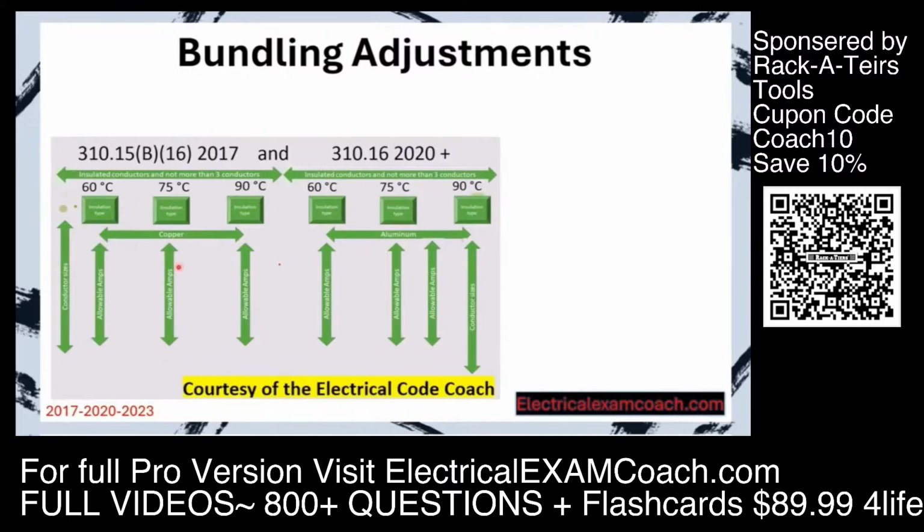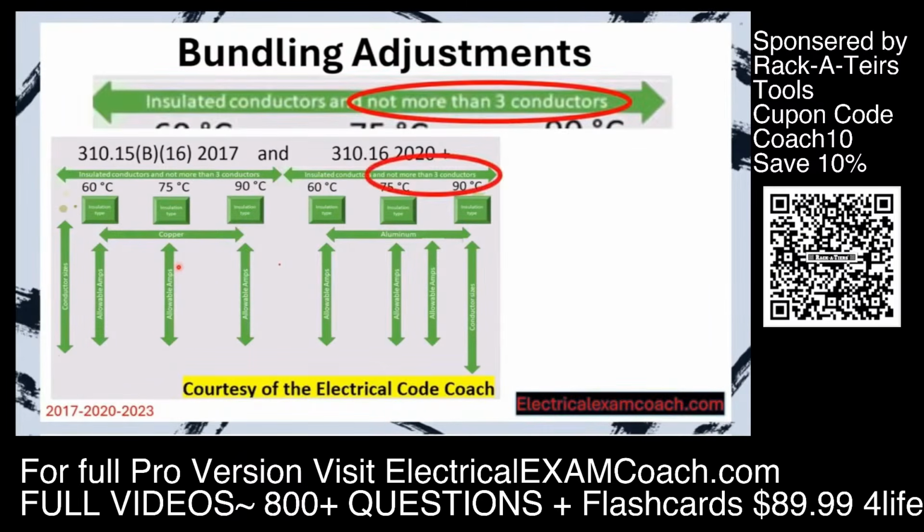If you look at the paragraph above the table, the one that I said we would come back and look at later, it's got some parameters there. It says, hey, these are the ampacities of these conductors if, and the first if that we're going to look at is if there are not more than 3 current carrying conductors inside of a cable, pipe, or even buried in the earth together. Let's take a look at it.